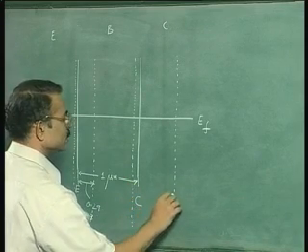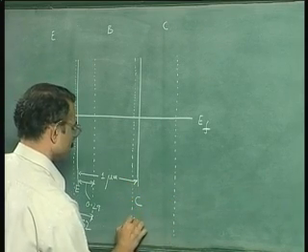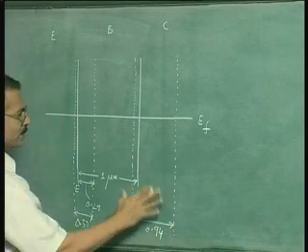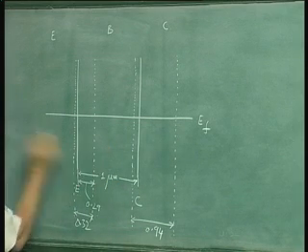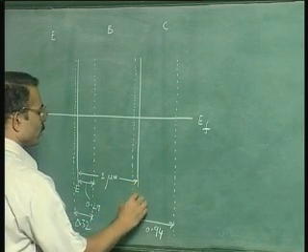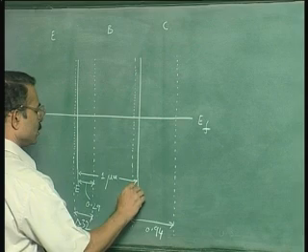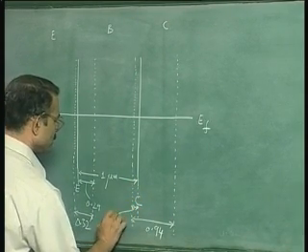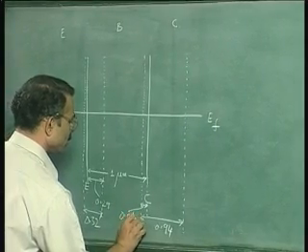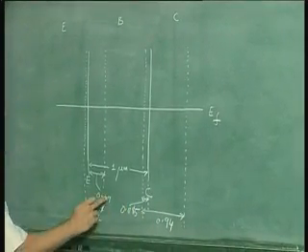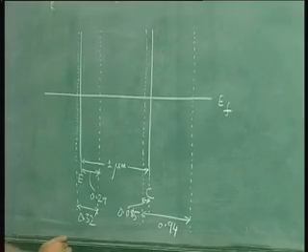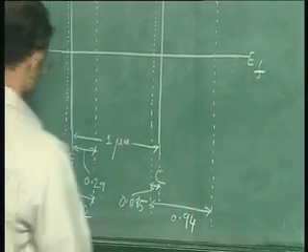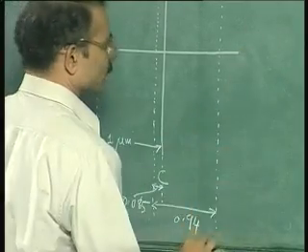So this distance is 0.94. So this depletion width, collector depletion width, is more than emitter base depletion width, out of which here this distance is 0.085 microns. All values are in microns. Okay, having located the depletion regions, let us extend this EF a little bit more.